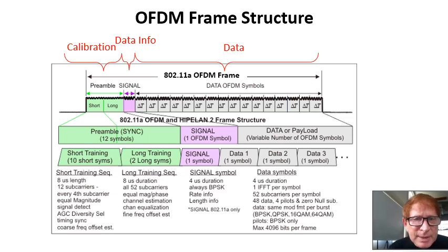The symbol transmission for the set of modulated subcarriers occurs in a repetitive manner to form what's called a frame. An example of a frame is shown here for 802.11a. The frame is important to OFDM because there is a preamble to each frame where calibration information is sent across the channel to allow modeling of the channel's influence on the transmitted waveform.